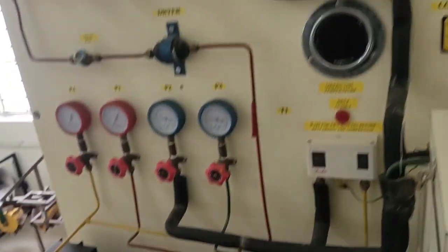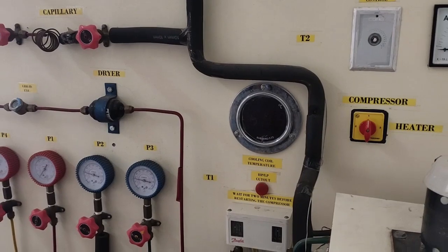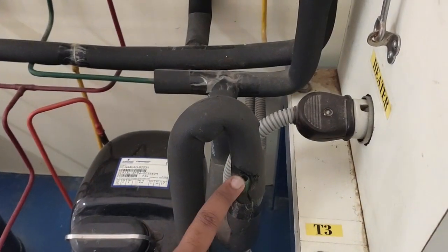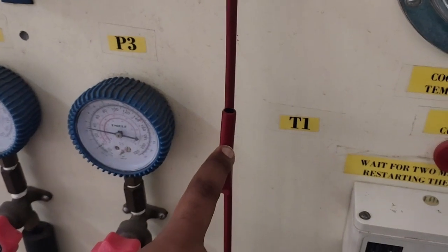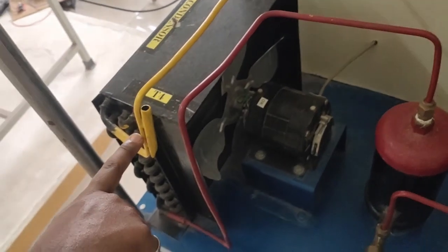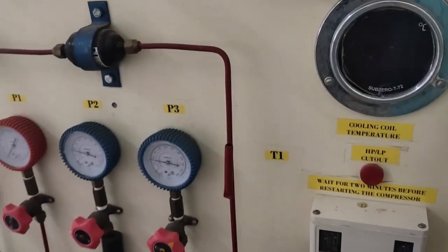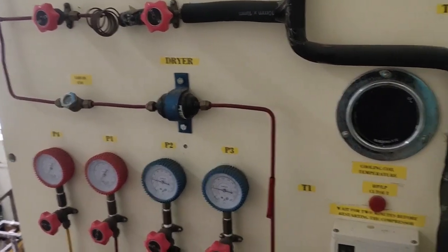So you have to fill the chilled water calorimeter with pure water so that the evaporator coils are fully immersed. You will have provisions for thermometers. Here on this provision you can measure the value of T3. Here you can measure the value of T2. Here the provision is for measuring T1, and here the provision is for measuring the value of T4. So this is the condenser temperature, this is the compressor temperature, this is for the expansion valve temperature, and this is the evaporator temperature.